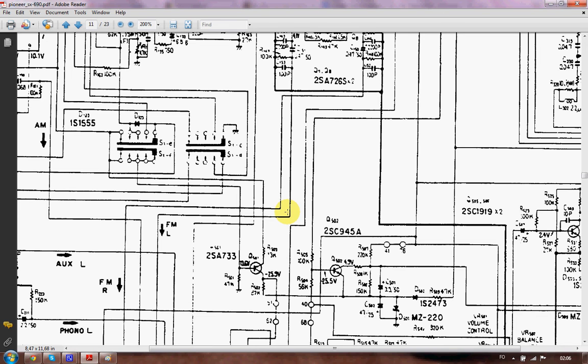Well, that's certainly going to imply that you have some sort of complication with your amplifier circuit. If you have a problem with your left channel, there's going to be a problem with your left channel amplifier circuit. It can even be due to dirt in some contact. That's a typical failure. Try to put a lot of contact cleaner in all the contacts and work them around. And if you have no sound whatsoever, there's likely a problem with the supply voltage to the amplifier, which is going to be direct current.